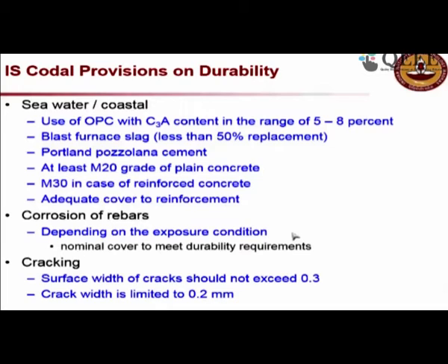Now, corrosion of rebars depends on the exposure condition, the type of concrete, etc. For the same concrete, if you want a longer life, we increase the concrete cover. Either increase the concrete cover or increase the quality of the concrete. Either way, we can enhance the corrosion resistance of the structure.